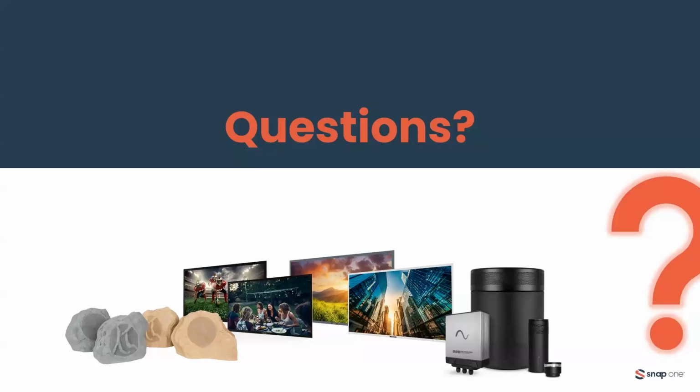There's a question here. Is it safe to say that high impedance speakers would be used for larger systems, or is it possible that a 4-ohm, 8-ohm system could be used too? So yes, it is definitely possible to use 8-ohm speakers in outdoor environments. As Brett was saying, the challenge there is that you can't daisy chain oftentimes more than two 8-ohm speakers off of a single channel, because it'll drop the impedance too low for the amplifier, and then the amplifier will go into a protection state. But you could do multiple zones off of an 8-ohm amplifier to multiple pairs of speakers.